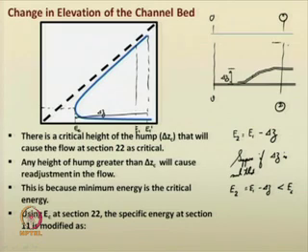The critical depth will be followed here, and then it will change the upstream conditions. You will see the corresponding depth y 1 dash; this was the actual depth y 1.